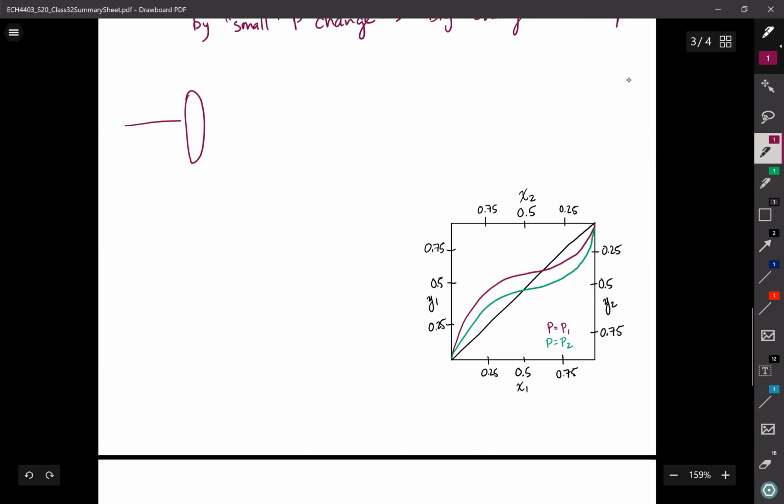So let's say we have a mixture that is 25% component 1. I'm avoiding using our usual component A because typically we refer to component A as the more volatile. Remember, there is no more volatile component because it switches. So let's just say 0.25 is component 1, meaning 75% is, of course, the other one. And let's say I have a feed. I'm not going to assume a basis, but I'll assume that the flow rate is known.